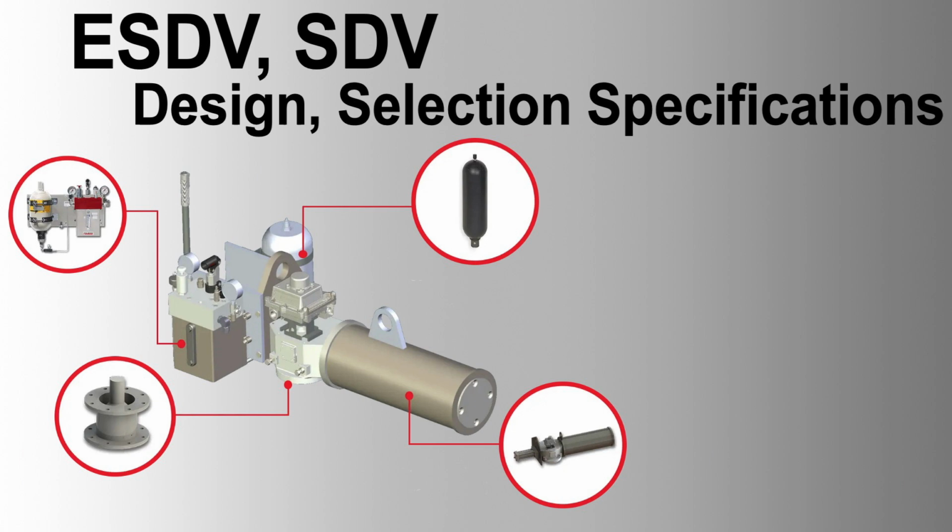Actuator sizing basis, safety factor: must deliver twice the required valve torque thrust for ESDV, BDV applications, ensuring sufficient power to operate the valve under maximum differential pressures. For on-off applications, a minimum of 1.5 times the calculated force is required. Operating range: must maintain torque margin over the normal range of operating pressures.